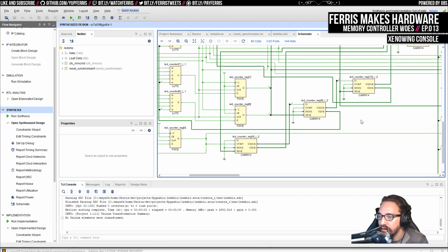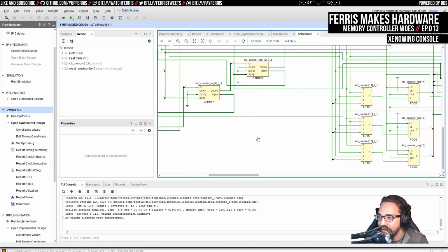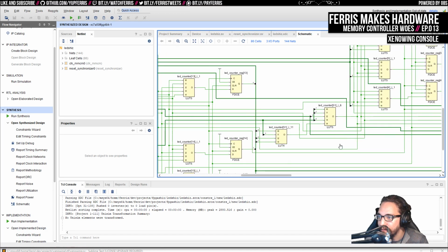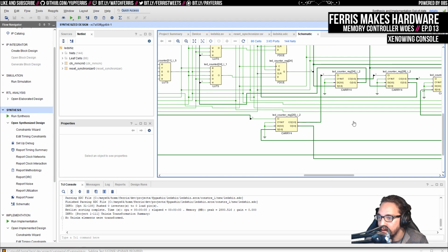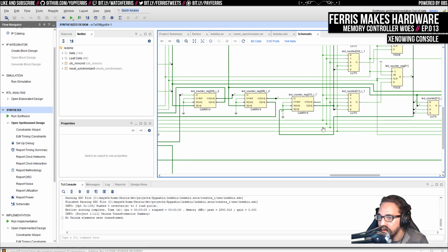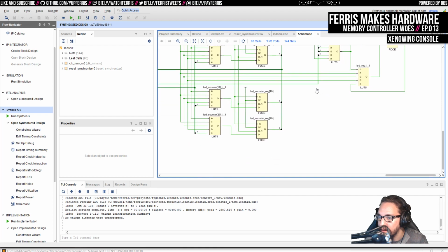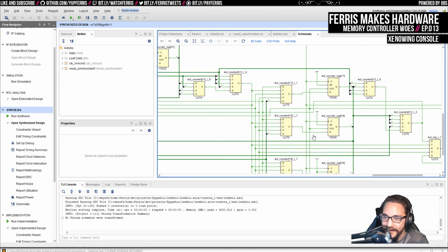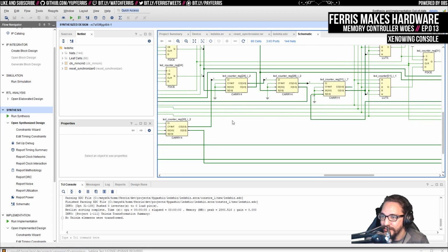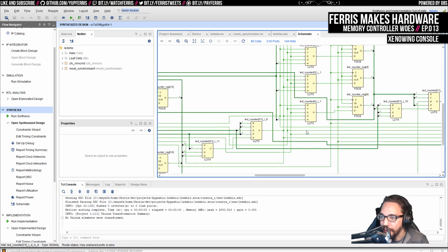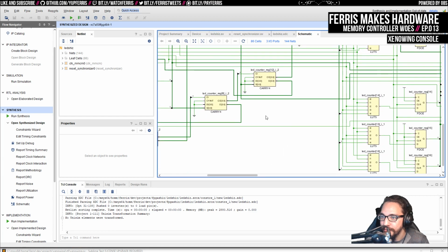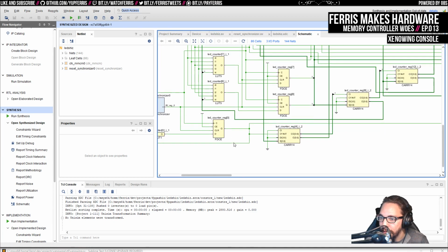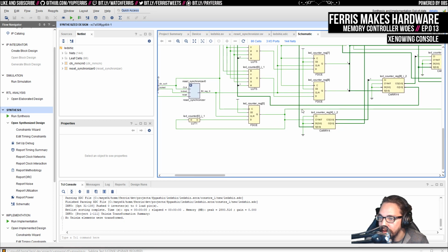I kind of want to see it, but it's actually not that important. It's just kind of interesting. Yeah, I'm not sure where it is. It's in here somewhere, representing that very lowest bit that we're adding being 1. And in fact, it might even not be that. It looks like there's a logic block here, and this carry comes from this. So it might actually just be a little inverter, which is probably what this LUT is doing here. That's probably what that is actually.